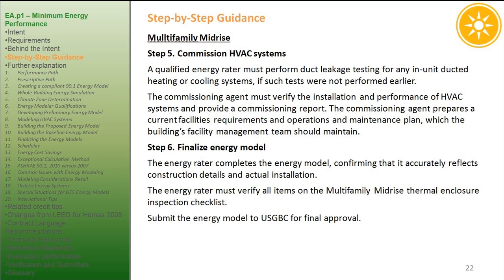Step 6. Finalize energy model. The energy rater completes the energy model, confirming that it accurately reflects construction details in actual installation. The energy rater must verify all items on the multifamily midrise thermal enclosure inspection checklist. Submit the energy model to USGBC for final approval.